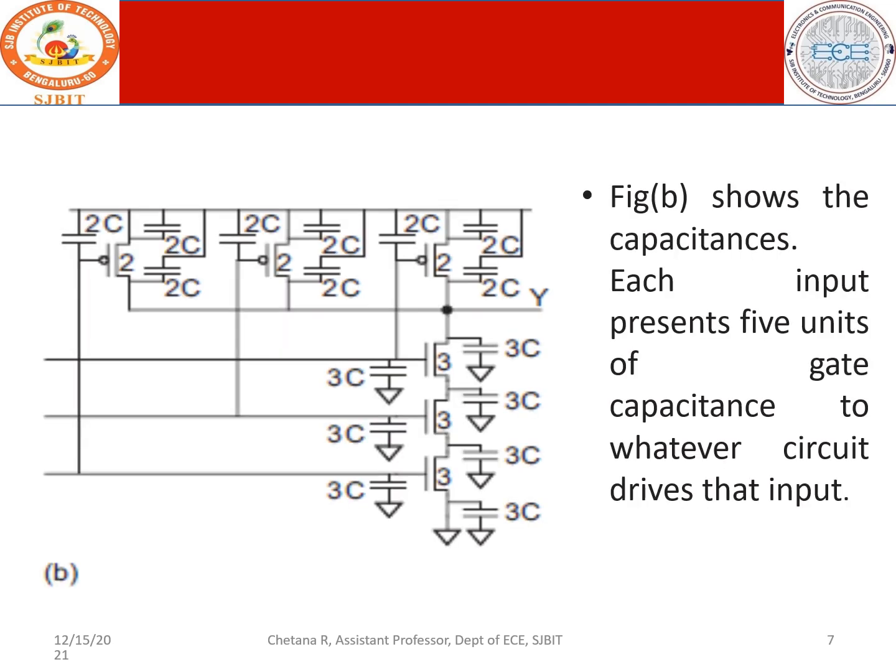So this is how we have the representation with respect to the capacitors alone. You have three PMOS transistors with the width given as 2, and the 3 capacitances associated are the source, drain and the gate. So the 3 capacitances are shown as 2C, 2C, 2C. Similarly here the width is 3. Therefore here also we have 3 capacitances: one is the gate, one is the source, and the other one is the drain. Like that it is in 3 series. Therefore we have the respective capacitances.